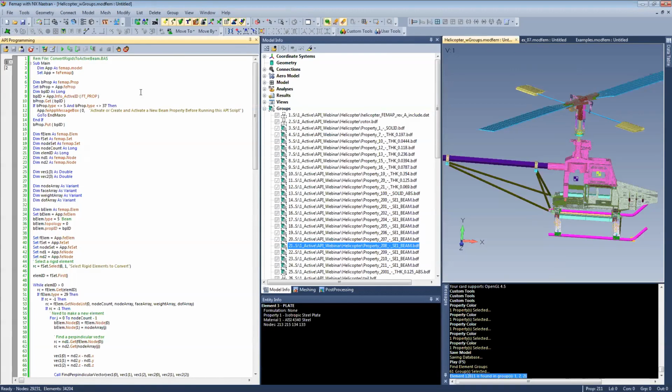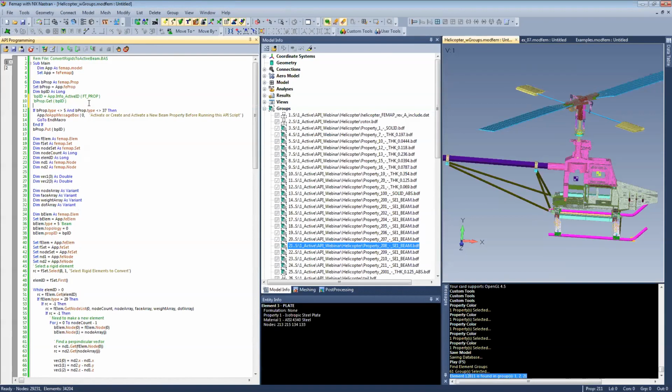I'm going to comment them out by putting an apostrophe at the beginning of the line. That means the code is still there. If I screw it up or want to go back, I can just uncomment it and delete what I added. And then I'm going to add my own lines. So instead of the get and the active, I'm going to use, as you see as I type, as soon as I push that period, it brings up some of my options here. And I know that I want to use SelectID as my method.